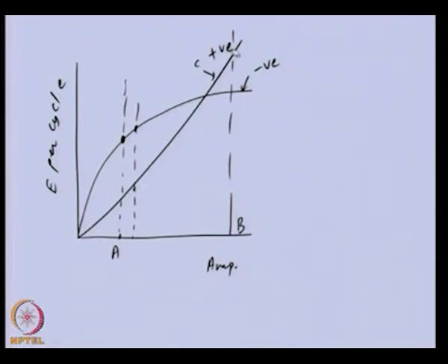So, the dissipation of the energy in this particular case is more, because positive damping dissipates the energy. From here to here the energy is getting dissipated, that is more. So, this much energy is getting dissipated in this particular cycle. So, we expect that the amplitude which is B here will go toward this side. Here the amplitude is less, but still the energy of dissipation is more than the energy of input into the system here. So, again it will go toward this side.